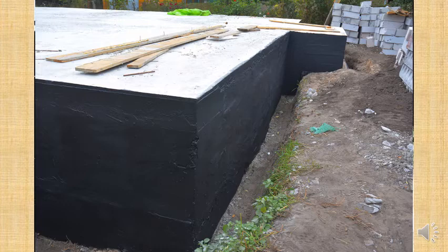Guys, this is actually something that you really need to start doing a bit more of when you build houses in Kurdistan. Often you're not painting the parts of the house that are buried underground, and that creates issues with water getting in under the house and then through the house. That's why houses in Kurdistan, one of the reasons why they're so damp. The other reason is that you're using breeze blocks, which we talked about in masonry.